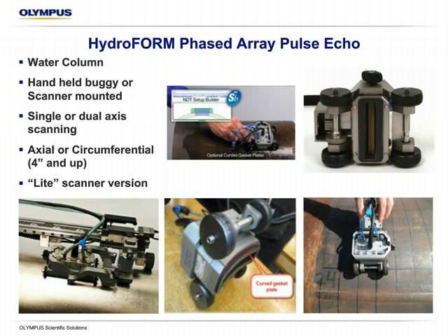We are able to offer that for scanning in the circ direction or down a long seam. The traditional catalog will be designed for 4 inches and above on a circ diameter, and the long seam is really something we assess, and then we decide which diameter of curved plates is needed for it. This is also single or dual axis, so we can scan in a straight line and record the data. We can scan without an encoder, or we could do XY mapping with either a scanner or just manually manipulating the probe.